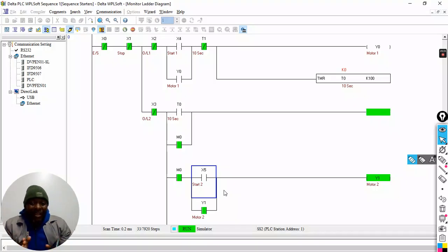That's after a further 10 seconds. I think it meant to say 10 seconds after starting motor 2, motor 1 should stop. If that had been said, it would have made life very easy. You start motor 1, and it does not matter how long motor 1 runs for. As long as it's after 10 seconds, it could be after 100 seconds, you could start motor 2. If you then start motor 2, 10 seconds later motor 1 will stop.